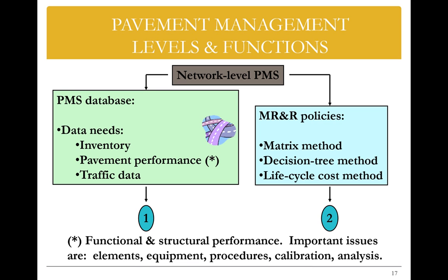as well as pavement performance. I'm putting an asterisk here for what I mean by pavement performance: both functional as well as structural performance. I mentioned this in chapter 1. To remind you one more time, structural performance is how sound the pavement structure is, so that it can resist the amount of traffic for several years to come, versus functional performance, which is how smooth and safe it is to drive on that pavement structure. So there are two types of performance.